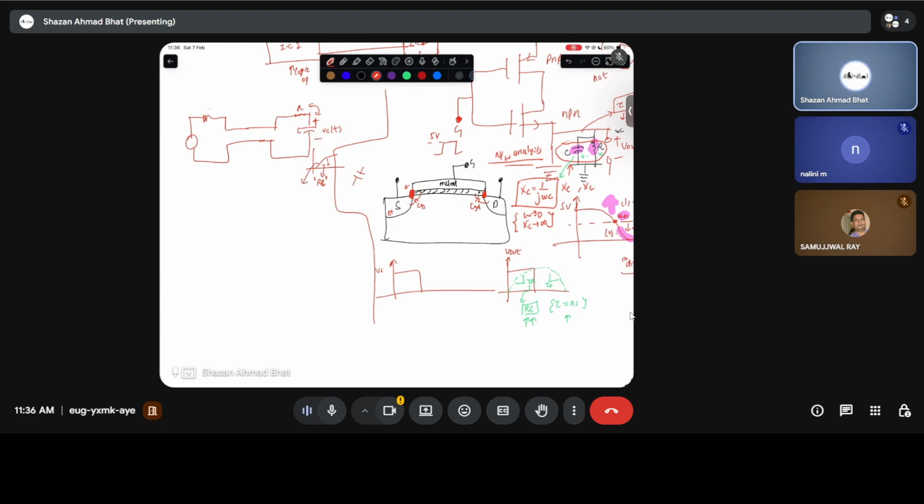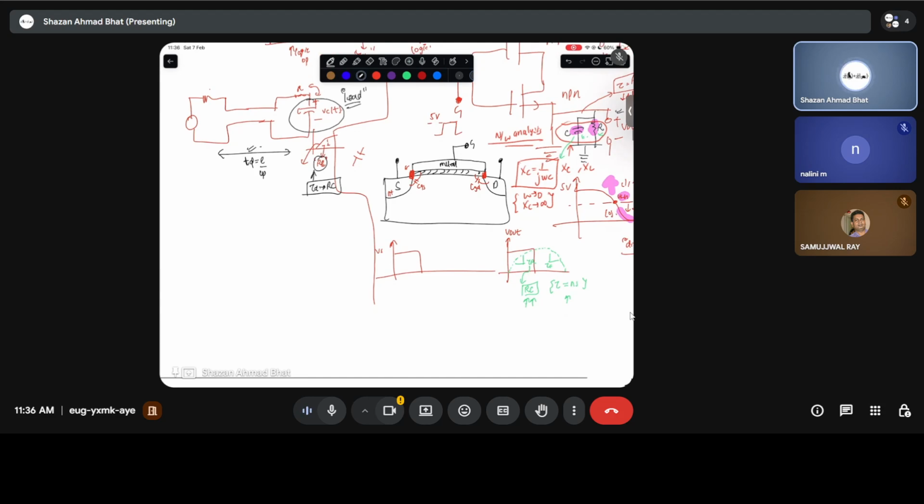So this is going to determine the rise time of the voltage. Note that this is not the delay time associated with the transmission line. So this time delay is different. So this is the time delay which is equivalent to the length of the transmission line divided by the phase velocity of the wave moving through the transmission line. This time delay is different. It depends upon the RC value. It is basically intrinsic to the load. And it adds on a time delay over the time delay caused by the transmission line. Okay, so this is the separate time delay. It's not the same time delay we are talking about.